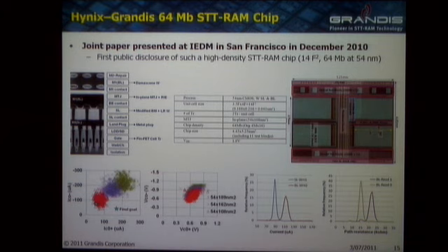So that's where we were in December. But I think within the next few months, hopefully in the second quarter, when we put the dual MTJ devices in this chip, this should go very high, above 99.9%. So I hope we can get fully functional chips from this process very, very soon. Here you can see a few devices shorted. So there's about 1% of those at the moment.